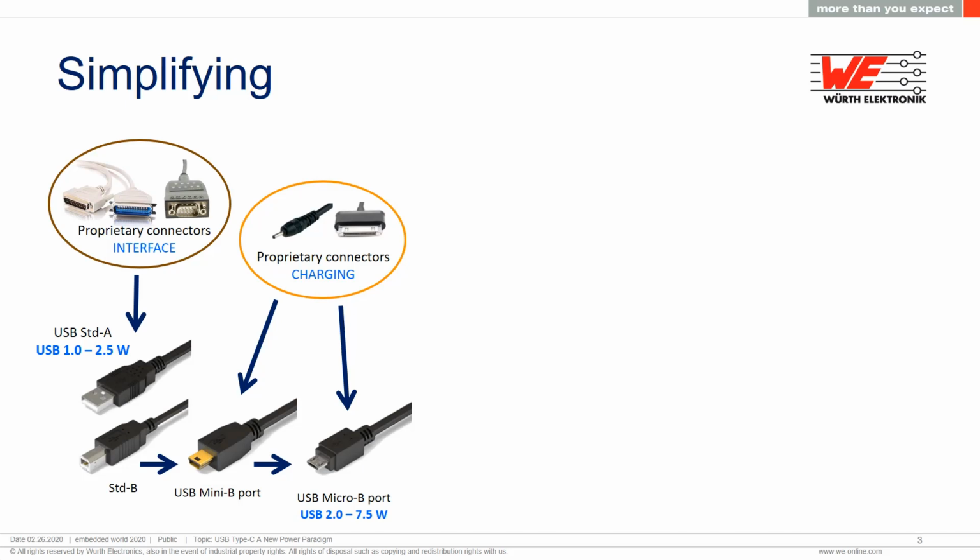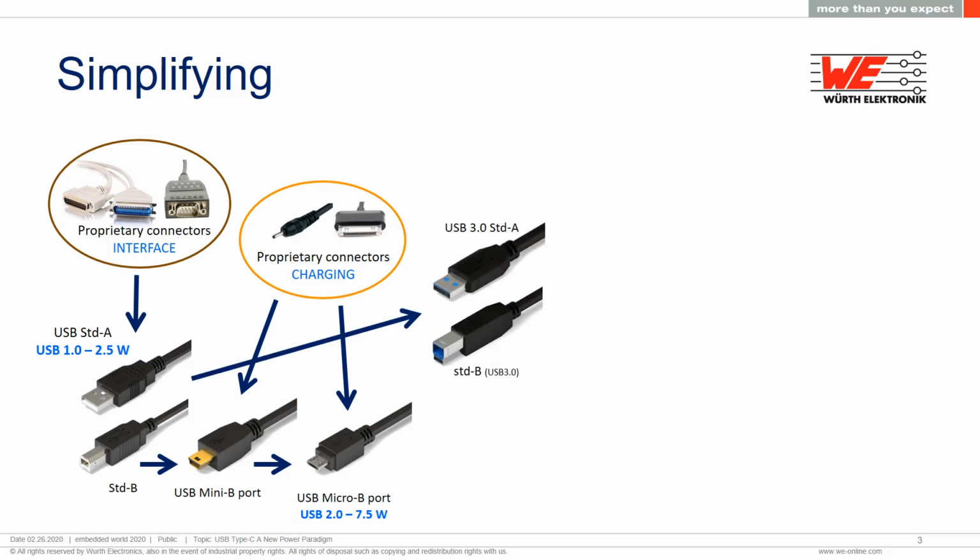People were transferring more data with external drives and USB sticks, so the speed needed to increase. To do that, they had to add more contacts for more data lines, going from 4 pins to 8 pins. This required new connectors at each end, which were introduced in late 2008 as USB 3.0. The Type A was backward compatible but the new large B end was too big to plug into many devices. So 2 years later, they introduced the micro USB 3 connector, and at the same time upped the transfer speed to 10 gigabits per second.